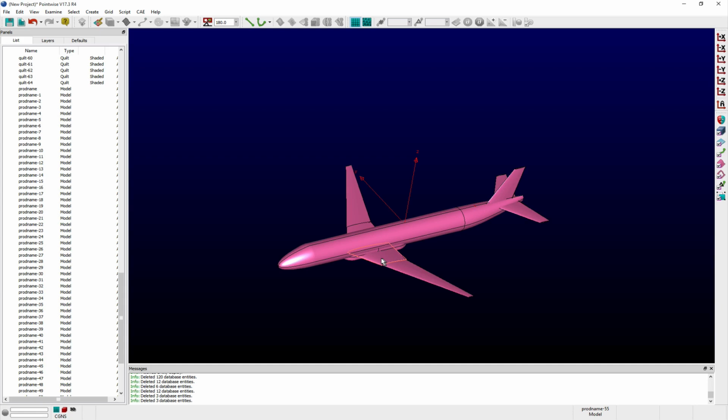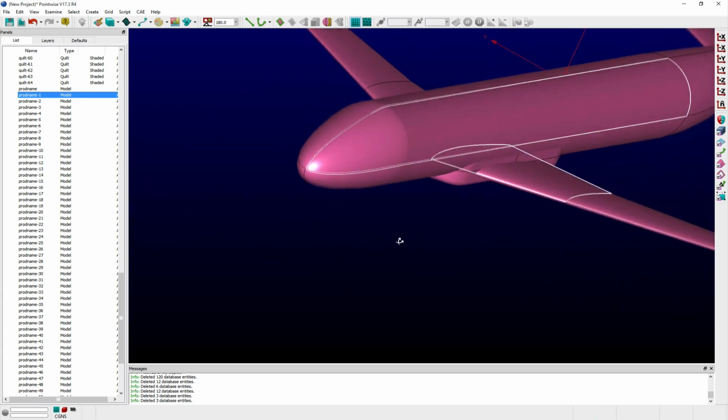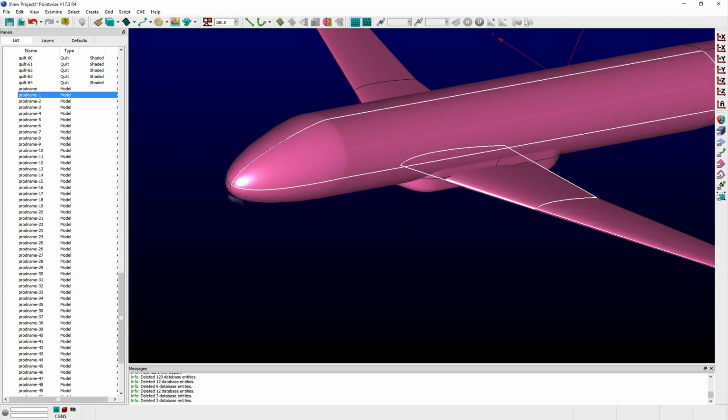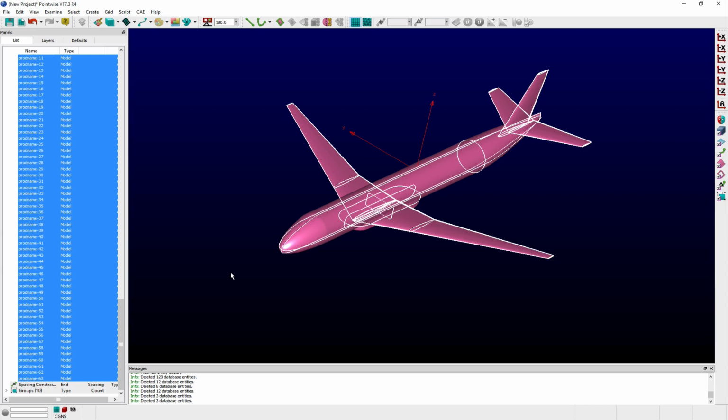When I select a few of these models, I also discover that the surfaces aren't trimmed with one another. For example, the wing is composed of 6 or so individual models, and the wing itself protrudes through the fairing attached to the fuselage, which are both themselves composed of separate models. To begin creating a single watertight solid model, I'm first going to select all of my models and combine them into as few parts as initially possible.